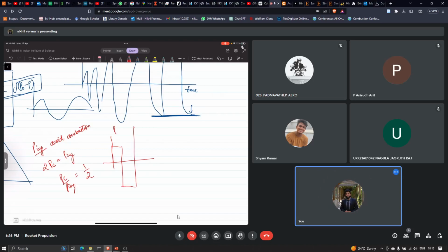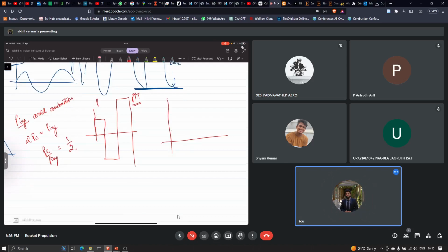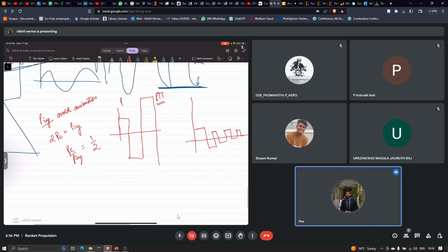The professor tells the relation like this. So the pressure increases, and in some cases, depending on the injection pressure, the pressure will catastrophically increase, right? In some cases, the pressure will decrease, depending on the injection pressure. So with that, the professor came up with this. He said that to avoid this combustion instability, your injection pressure should be greater than two times the combustion chamber pressure, right?